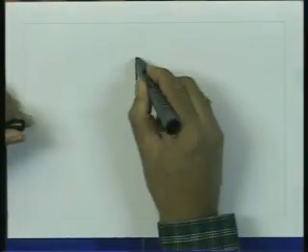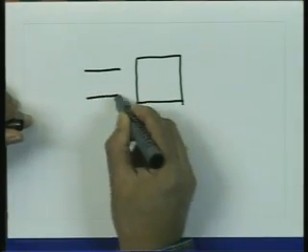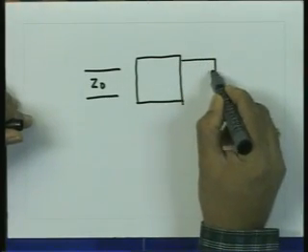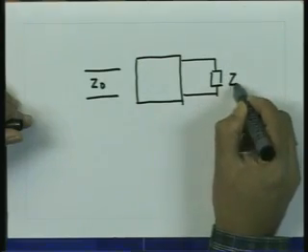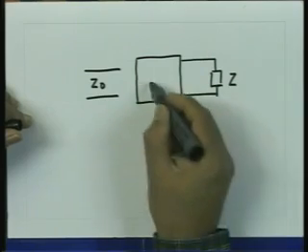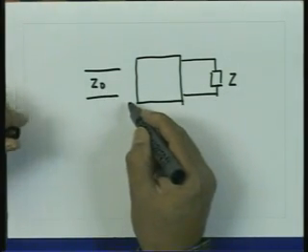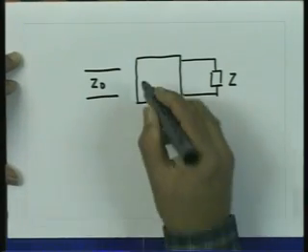So, essentially we want to introduce some kind of a module in between, what is called an impedance matching device, on one side of which we want to see the impedance which is equal to the characteristic impedance Z naught. The other side is some impedance which is not equal to Z naught. Through the impedance transformation unit, when impedance is seen, that should appear like Z naught. So, we are certainly using the impedance transformation characteristics of the transmission line inside this matching unit.